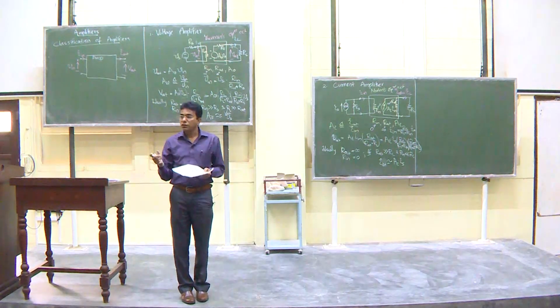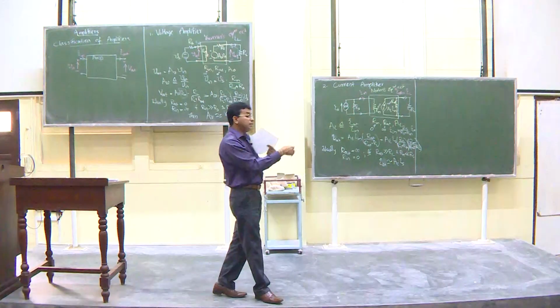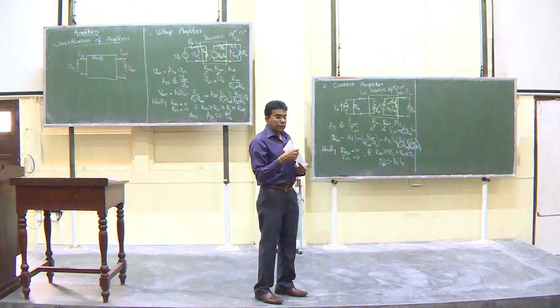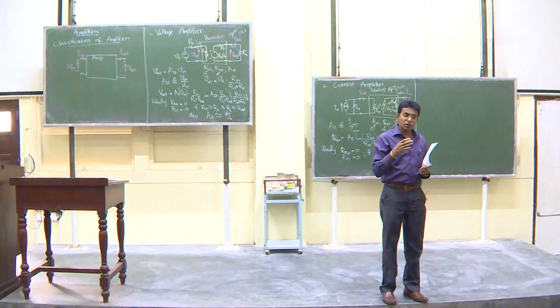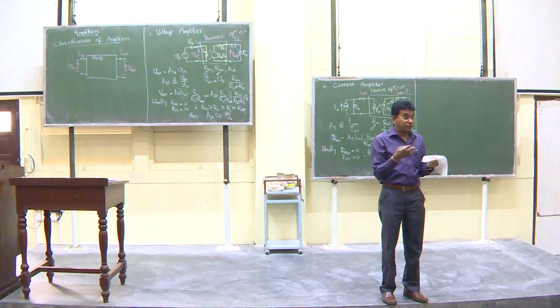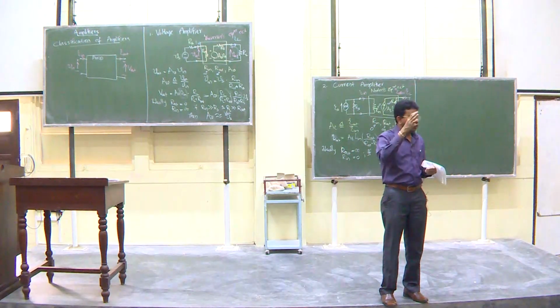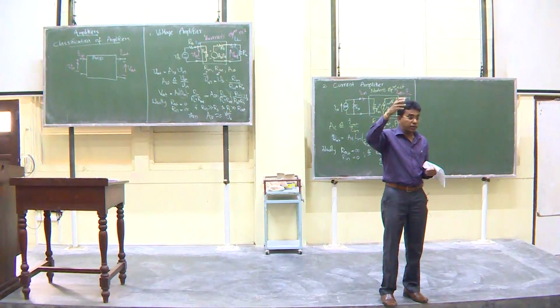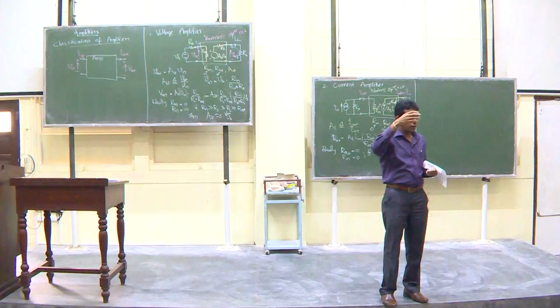Practically they are not, but we have to make them as large as possible and as small as possible. Typically when we say small, for resistors, the practical values are a few hundred ohms or less. Typically the resistors that we use are in the range of kilo ohms, like typically 500 ohms upwards, like 1K, 2K, 10K, 50K, up to about 100K.